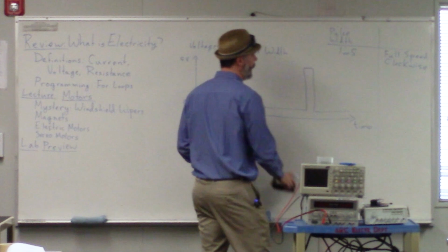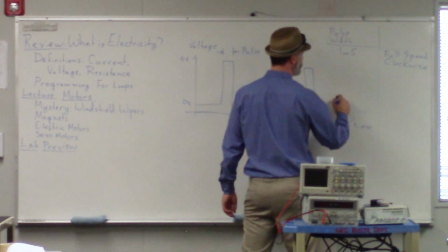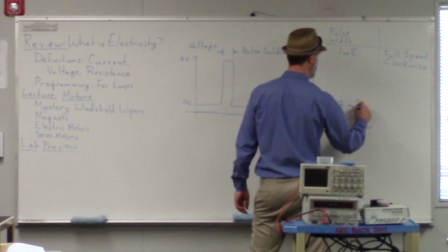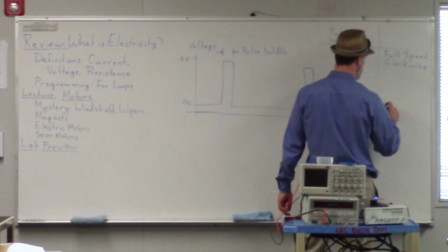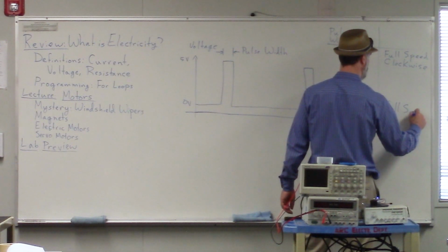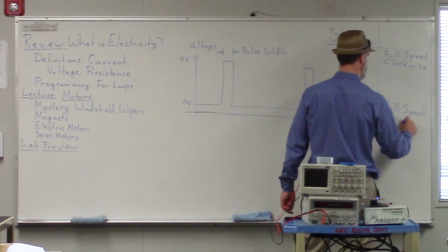And then if we have a pulse width of 2 milliseconds, that tells the motor to go full speed counterclockwise.